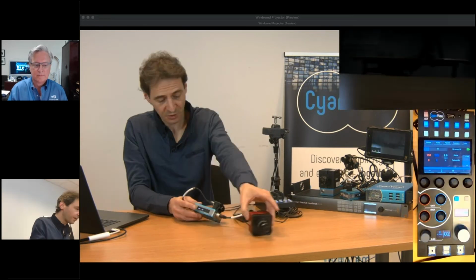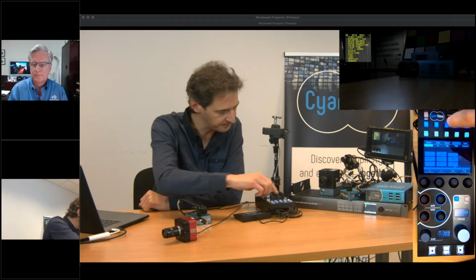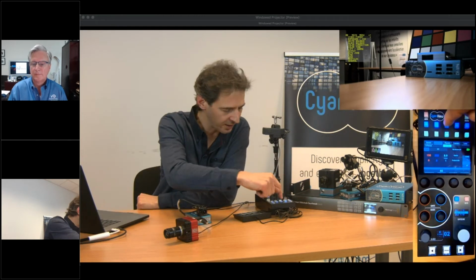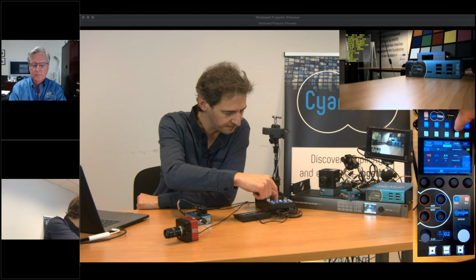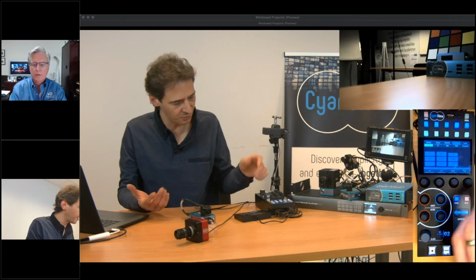This is the IO Industries camera. On that one, you also have OSD. You can enable the menus there. What happened is that I manually turned the iris there, so it was quite dark. So you can go to the OSD, you can change a lot of things in there. All the settings that are not available for the protocol, or that we don't necessarily support because some of them might make no sense, you go to the OSD, you can put that there manually.